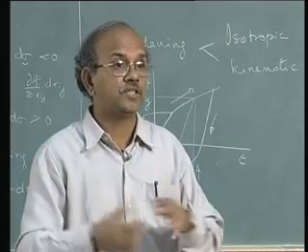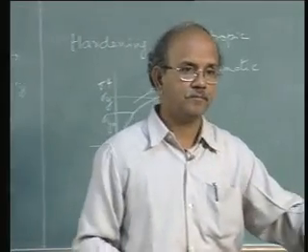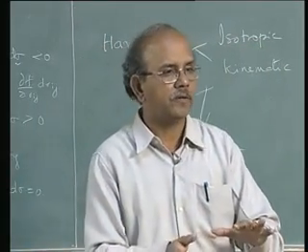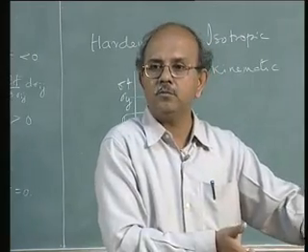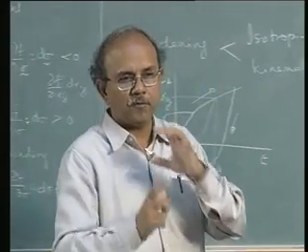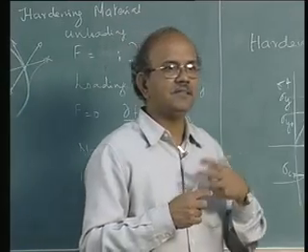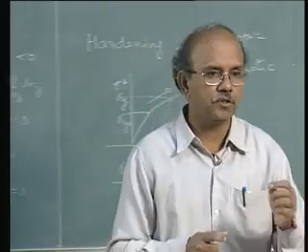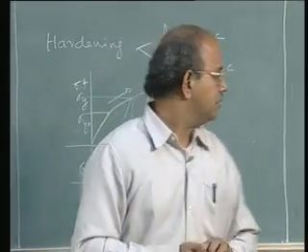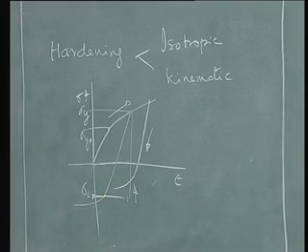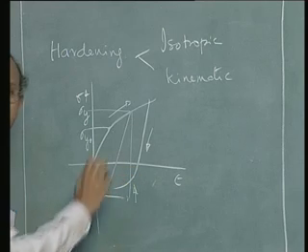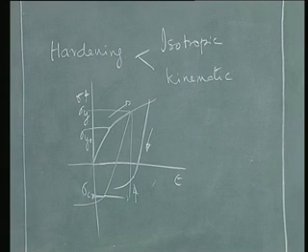So, less force is required in the opposite direction to move it now. Okay, you moved a guy like this, he is now facing resistance. You want to move him a bit in the other direction, it may be easier to move. So, from a very crude sense, this kind of entangling effect will have an opposite effect, or I would say opposite phenomena, for the load which now acts in the opposite direction. Hence, there is a climb of the yield point and it goes up.